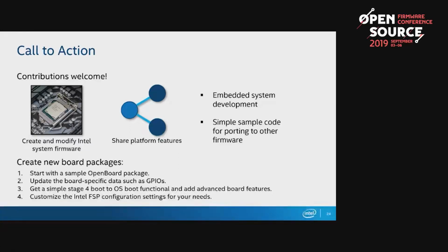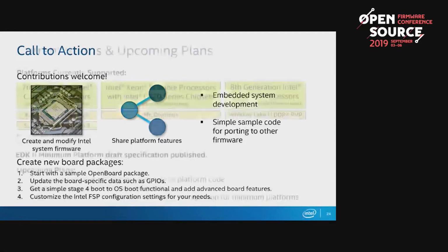So we encourage you to do a stage 1 boot, get your debug working. Do a stage 2 boot, get to memory init, and bring it up one stage at a time. And then in addition to that, you need to configure the FSP for your specific board. And so you can use your FSP integration guide to do that.